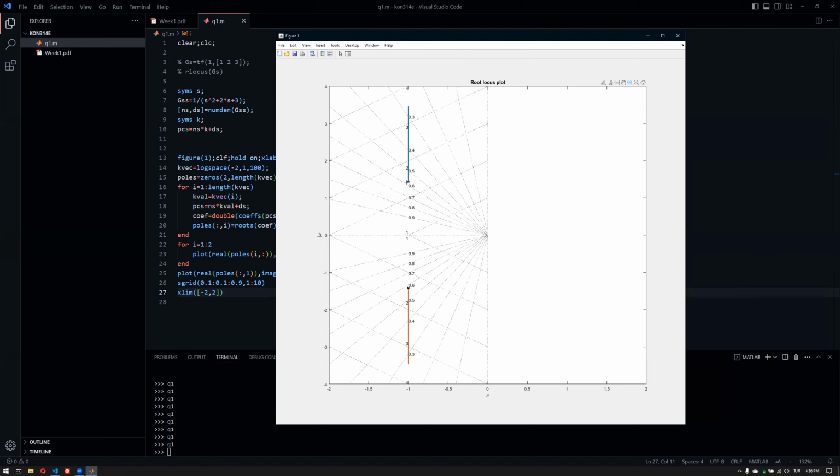Now you can see that our system starts with roughly 0.6 damping ratio. And when we increase the gain, we cross even lower zeta values. So zeta is decreasing. I said that this corresponds to a friction for the pendulum, for example. And the lower the pendulum faces friction, the more oscillations you will get. And the more oscillations, the higher the overshoot is going to be. So that's the reason why overshoot is basically increasing. Zeta is decreasing when we increase the K value or the gain.